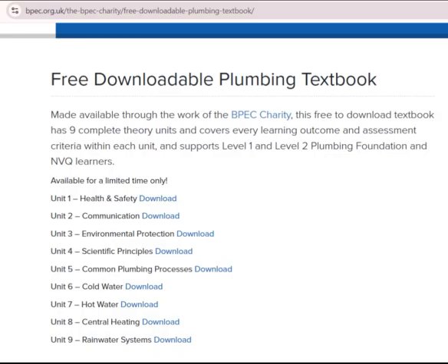Principles of a siphon. The principle of a siphon is to move water from a high place to a low place using only atmospheric pressure and the cohesive properties of water. In the diagram, the two containers are both at atmospheric pressure. But container A is higher than container B. This means that the pressure at container A will be slightly lower than container B.